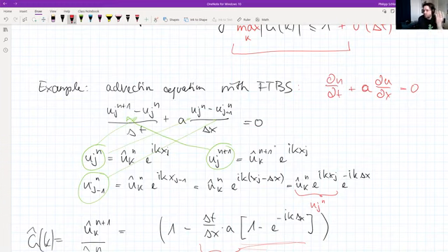So it could be 1 meter per second, 10 meters per second. Of course, the relevance of this A comes later on, if we then go into, for instance, Navier-Stokes or the Burgers equation. But if we just think of 1D Navier-Stokes, then this term would look like this: du dt plus u times du dx, and then you have some pressure terms and viscous terms and other things. Then, of course, in this situation, this convection speed would actually depend on the actual solution.